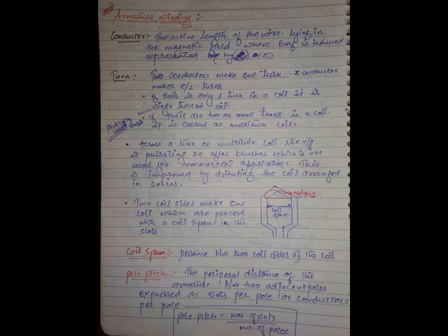If you go for double layer winding, this is the standard double layer winding. If you are not given anything in the problem, simply take it as double layer winding. Then you have to take two conductors in one slot, two coil sides in one slot. So in this, how many slot armature do you require? 30 slot armature is required. So here, how many slot armature are required?